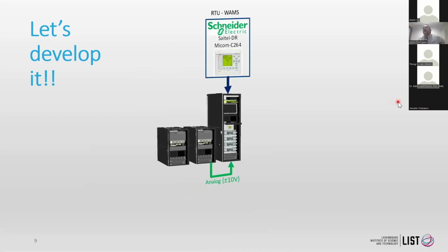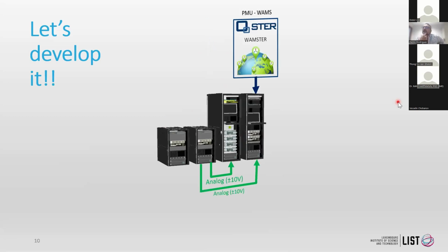And now we need to connect here the equipment that is connected in the grid, okay? For example, the RTUs from Schneider. In this case, our colleagues from Schneider adapted the RTUs that were physically installed in the grid to be able to transfer signals to our grid simulator. The same from our colleagues from Esther, okay? They adapted their PMUs so that our grid simulator was able to send signals to these PMUs in order for them to collect signals.